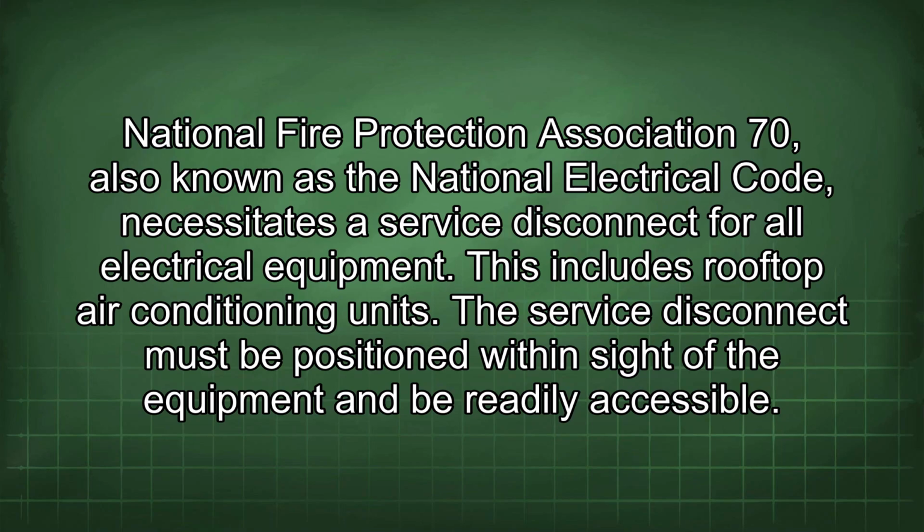National Fire Protection Association 70, also known as the National Electrical Code, necessitates a service disconnect for all electrical equipment. This includes rooftop air conditioning units. The service disconnect must be positioned within sight of the equipment and be readily accessible.